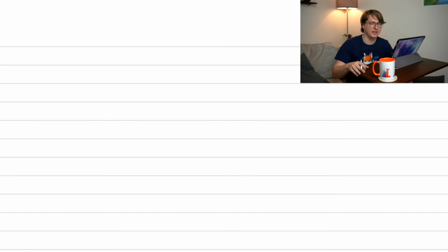So I'm going to go over an application really quickly. Imagine you have one of those old sets of speakers where it's kind of boxy and you can see the set of speakers in it. You have a big subwoofer down here all the way up to a little tweeter. Just with electrical components, how can you make sure that the subwoofer is getting all the bass while the tweeter's getting all of the really high-pitched noise? Again, all of these are meant to be better at different frequencies than the others. You need multiple of those little speakers to get the full sound. So things are better at low end, things are better at top end, and when they combine, it should be good. We can actually do that with alternating current, using inductors and capacitors.